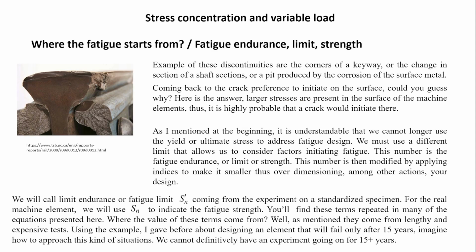Then, in the past, when we were dealing with static design, we considered the yield strength of the material to determine if the part is going to deform or not, and we considered the ultimate strength of the material to determine if the part was going to break or not. Is there something similar for fatigue? Well, the answer is yes.